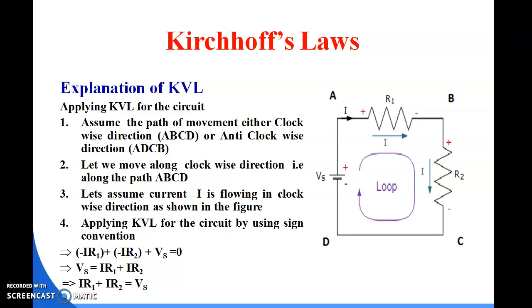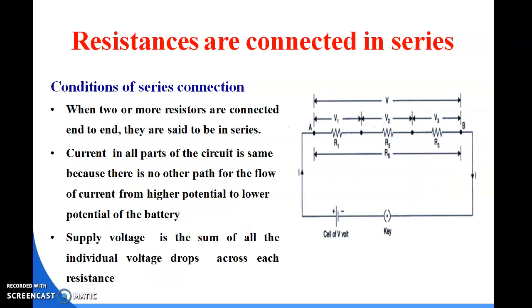That means Vs is equal to I R1 plus I R2, which implies I R1 plus I R2 is equal to Vs. That is Kirchhoff's voltage law.